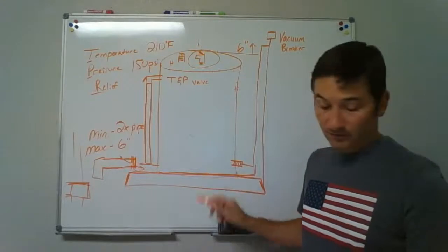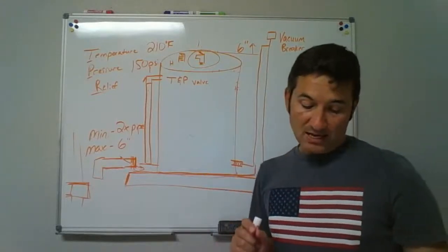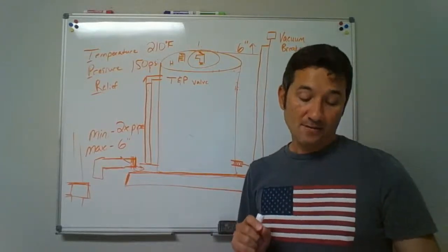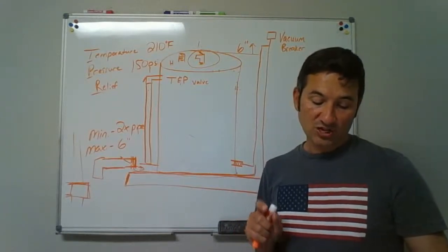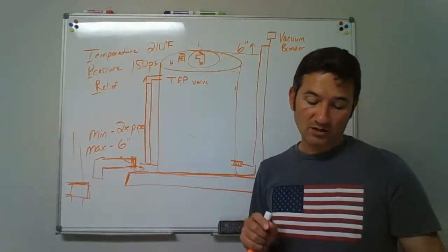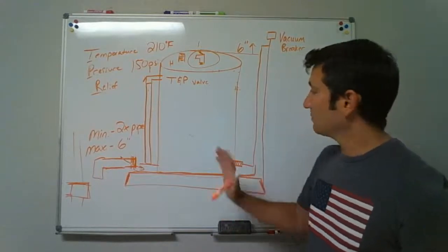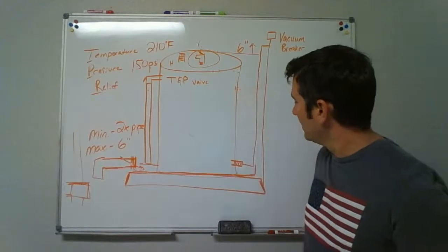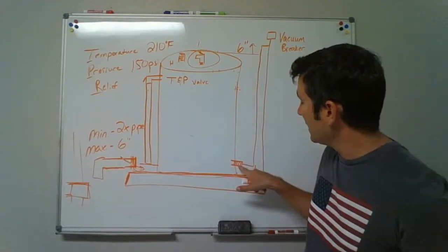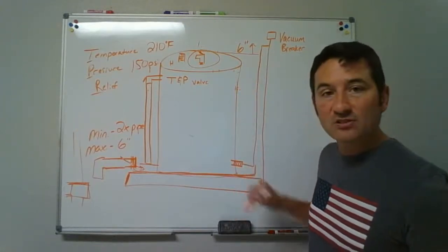The pan size and the drain. The pan itself shall not be less than 1.5 inches deep and shall be of sufficient size and shape to receive all dripping or condensation, anything from within the tank. So get that pan just a little bit big, to make sure that it can handle it if anything's off. We don't want a fitting hanging out over the side of the pan.